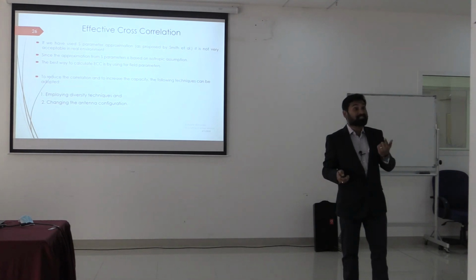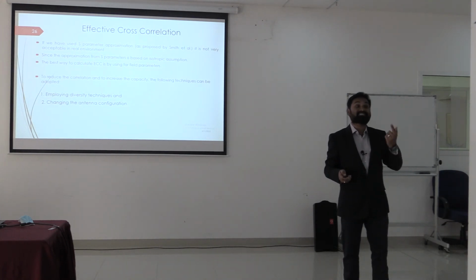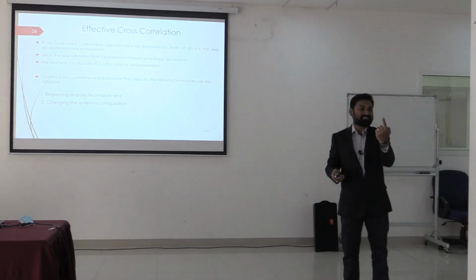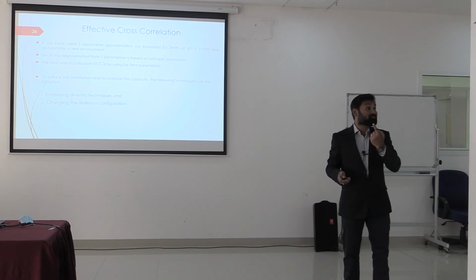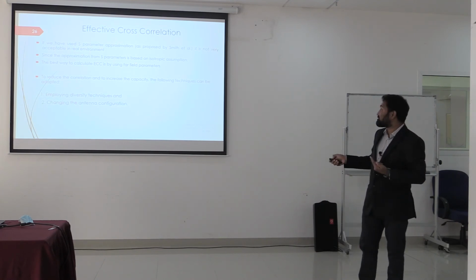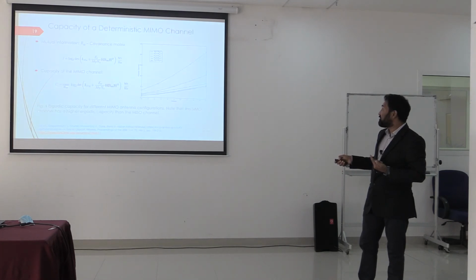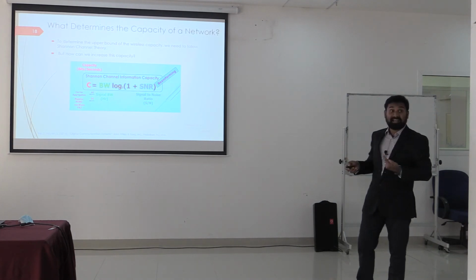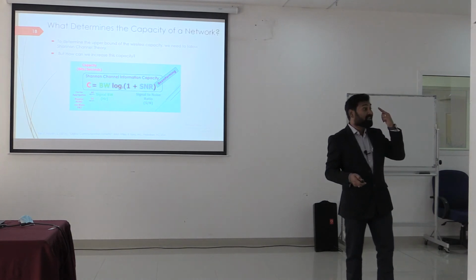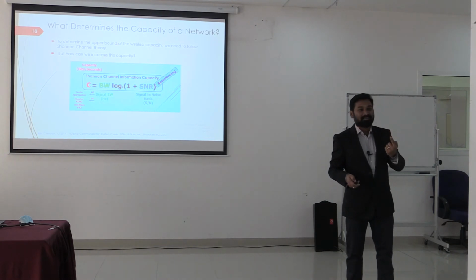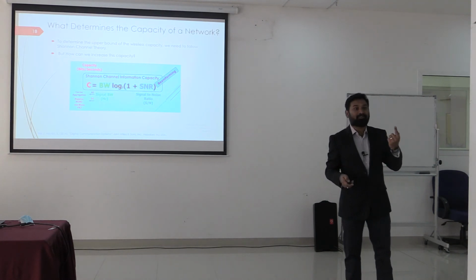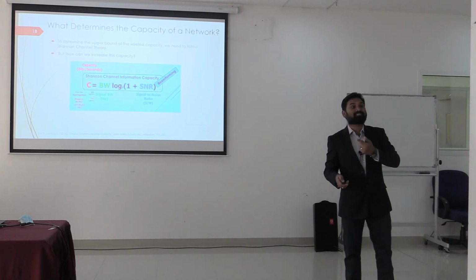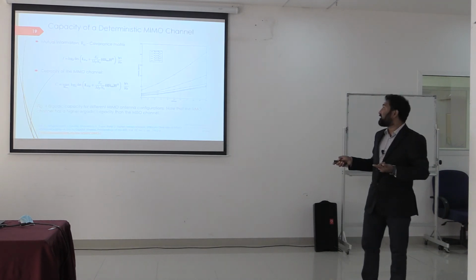The disadvantage of this S parameter approximation: during those days it was advantageous, since it is isotropically radiating its electromagnetic power, meaning it radiates uniformly in all directions. That is their assumption. But in 5G or in mobile communication, you have to create the beam. The desired power is directed towards the intended user, not to all the users. So you have to go with directional beam forming. So this S parameter approach is not a suitable approach to model your 5G channels.